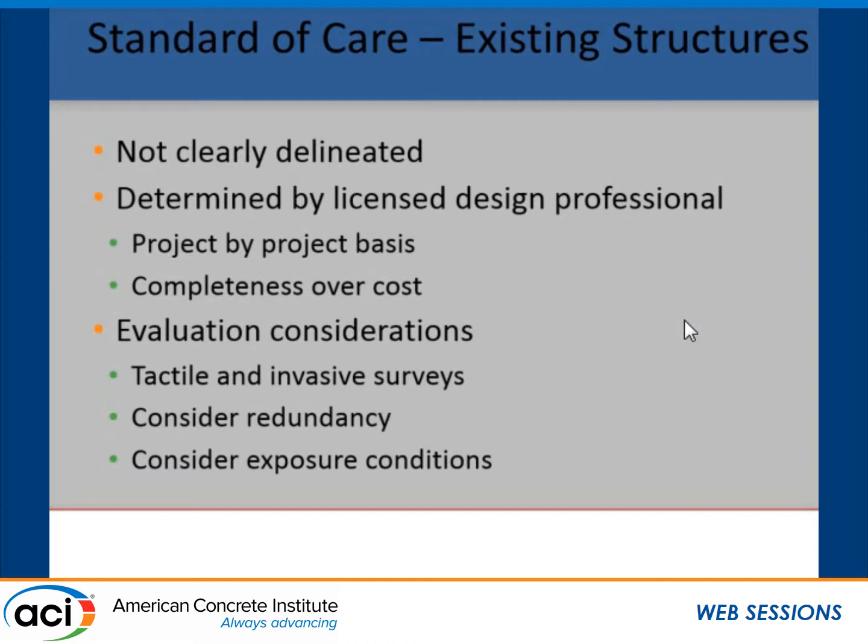If the owner really wants to get somebody to do a low-cost survey, let them do it. It's not worth, as Amonte said, being on the other side of the table, having to explain why you didn't investigate something. But in terms of evaluation considerations, you always want to do not just tactile, but when necessary, invasive surveys. We need to get into these structures because there's always going to be things that we can't see until we start taking it apart.